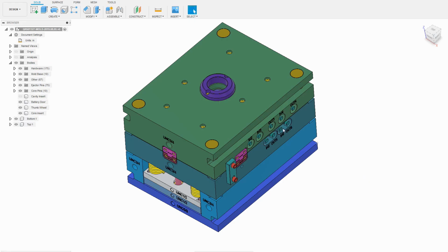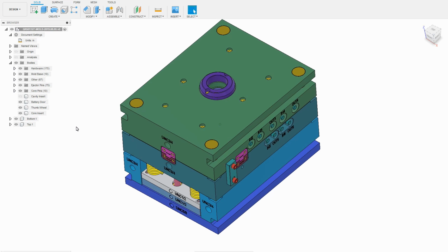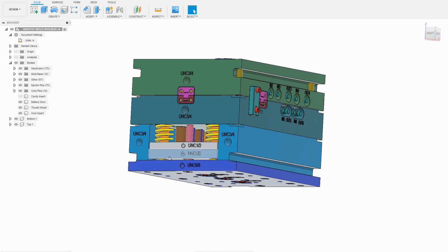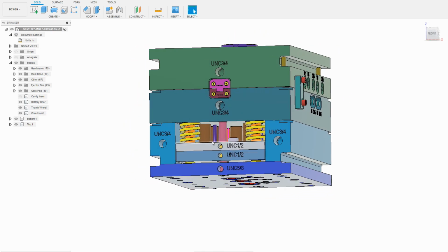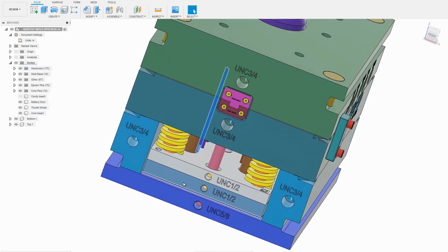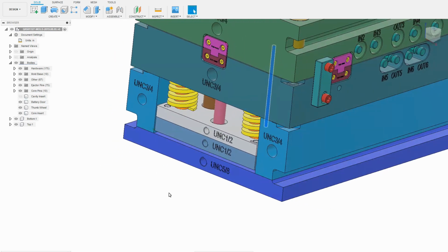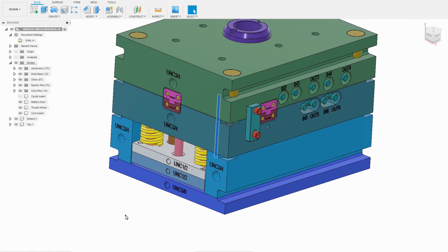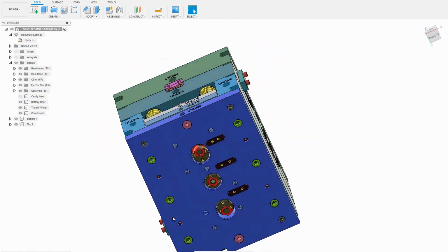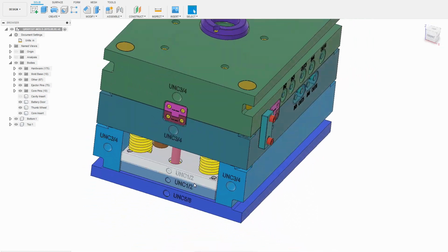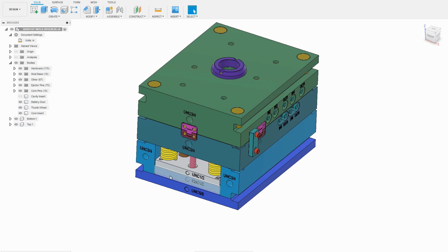Here's the injection mold itself, and one of the things that's interesting about this is just how many parts there are. You can see I've grouped them by different categories, and so we have close to 300 parts, or over 300 parts. What I'm going to do is hide parts of this, but first I'll give you an idea of how this works. Down here is the ejector pin mechanism. So we have a number of ejector pins like these here, I believe. No, actually not that. Maybe this one, I'm not sure which, that are connected all the way from down here up into the part. And there's some mechanism, I'm not sure what it is, possibly pushing through here, that pushes up on these plates and causes the part to be ejected.